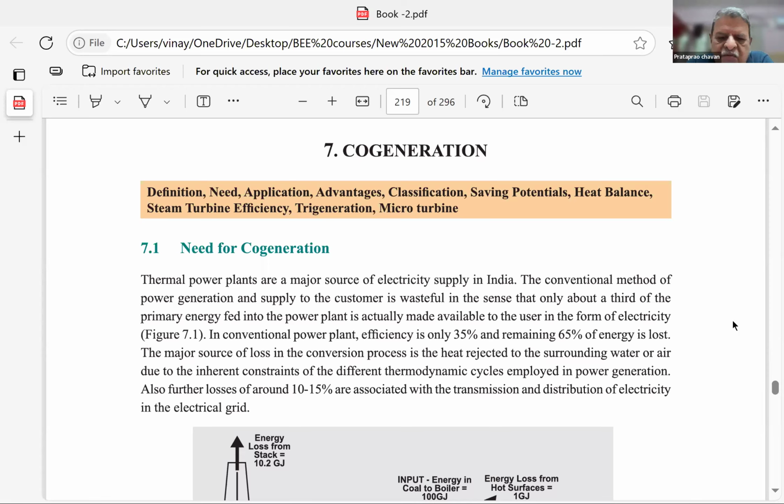Now, this bagasse is a waste product for sugar factories. But if you dry it, it becomes very good raw material for burning in a boiler. So if we use this bagasse, which is freely available, at most free of cost to the sugar factory, and burn it in a small FBC, fluidized bed combustion boiler, there your fuel input cost is zero.